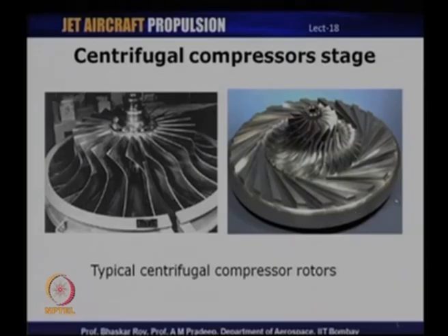rotor. So, these are two typical designs of centrifugal compressor rotors, and though the concept is still the same, there have been tremendous developments in terms of design and materials which are used in centrifugal compressor rotors, and that is why the modern one which I had shown has a much more sophisticated design, and which means that these compressors will be able to generate higher pressure ratio with a better efficiency as compared to what we were able to achieve in the earlier days of design of centrifugal compressors.